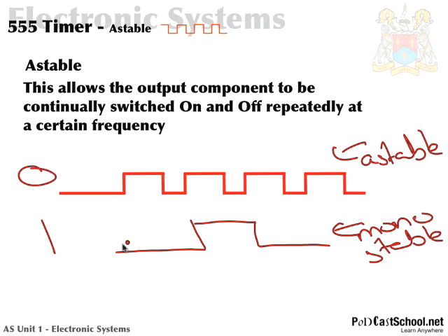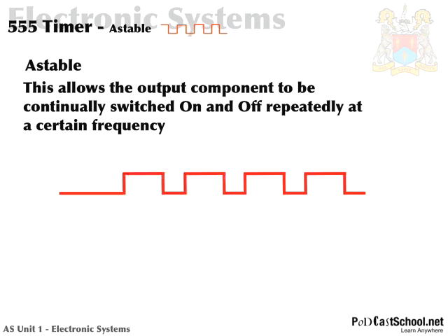By stable states, I mean states whereby we can say most of the time it's in one state. So in monostable, it's usually off and it's on for a time, but in astable, it's neither on nor off stably. It's on for a time, then off, then on, then off. So there are no stable states. Okay, so that's what we mean by astable.